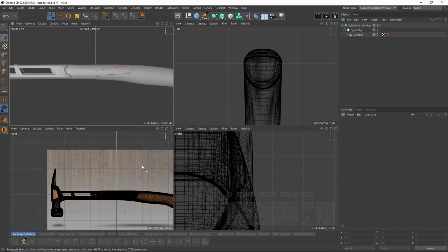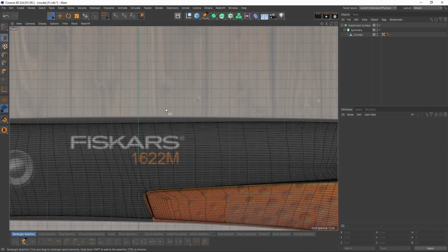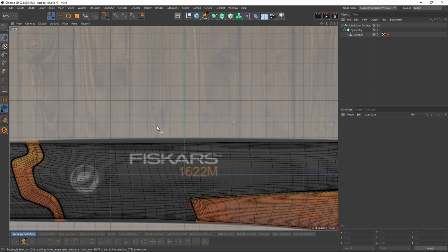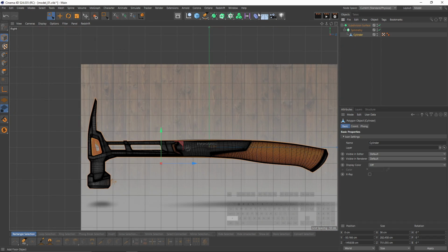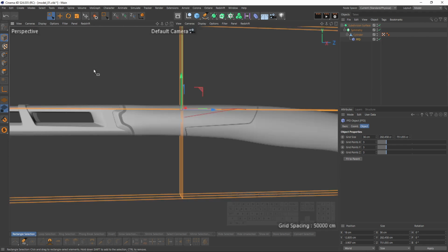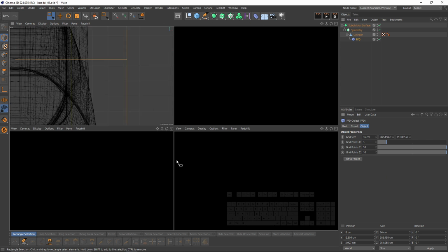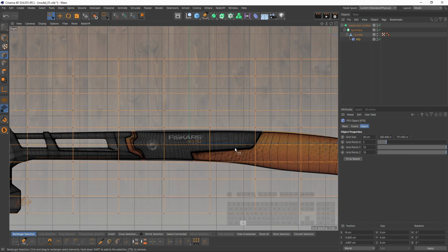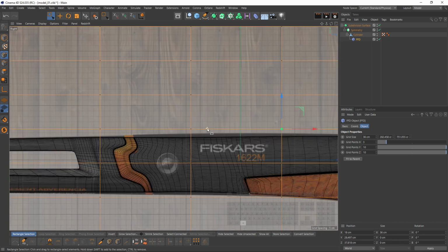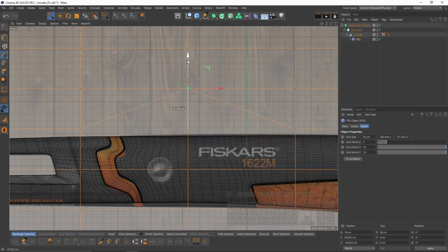Or the last thing, as you can see, we don't have a perfect match over our image plane. I can press Shift and add an FFD deformer. I will add a bunch of points on Y and Z. Then select points of the FFD and change my object.